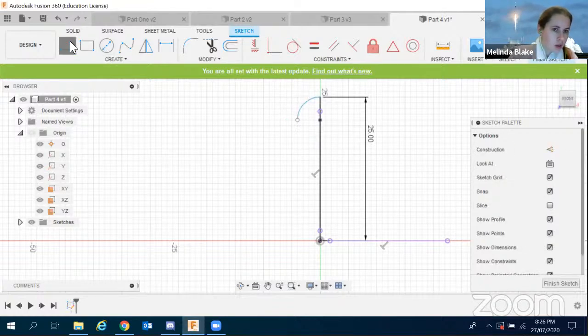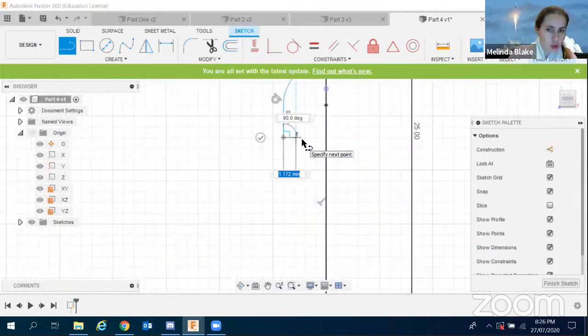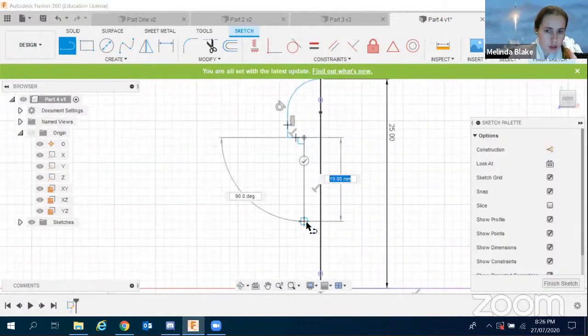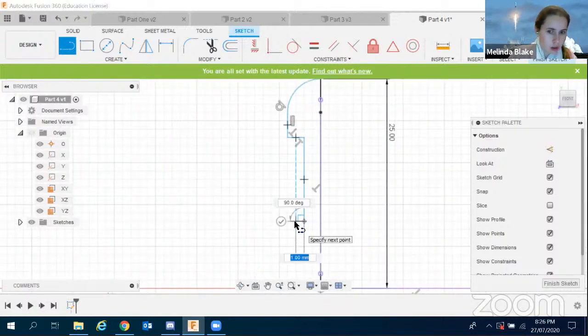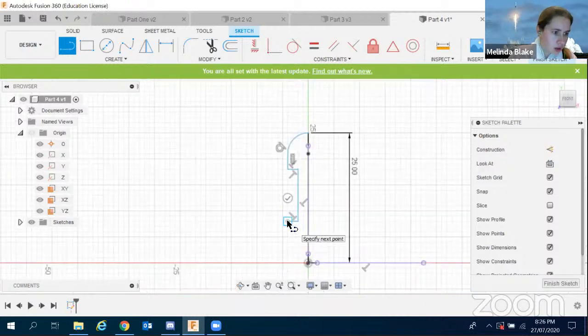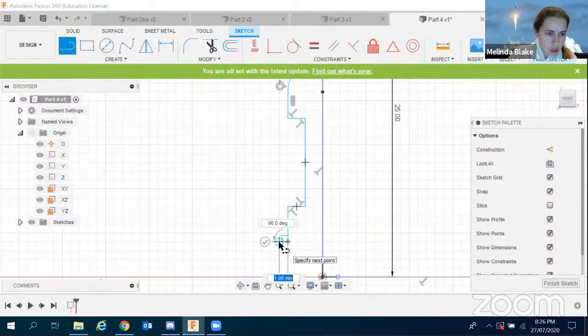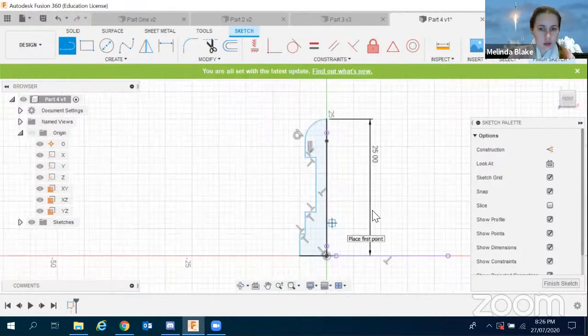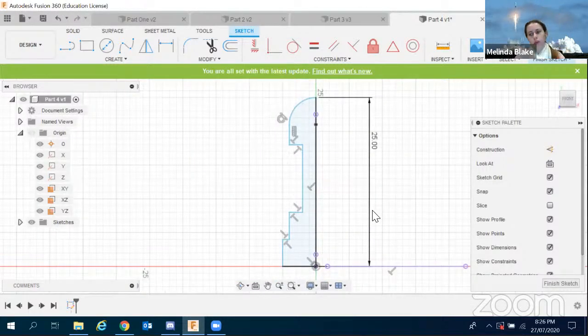Okay. Straight line tool again, it's going to come down a tad. We're going to go over. Remember, I said I'm not doing those radiuses in the sketch just to make it easier. So over, down, over again, down, and then it just steps out a touch, all the way down and back over, and that's the turn plate. So there's the shape that I'm drawing here. And I'm going to come back and put some dimensions in there in just a sec.